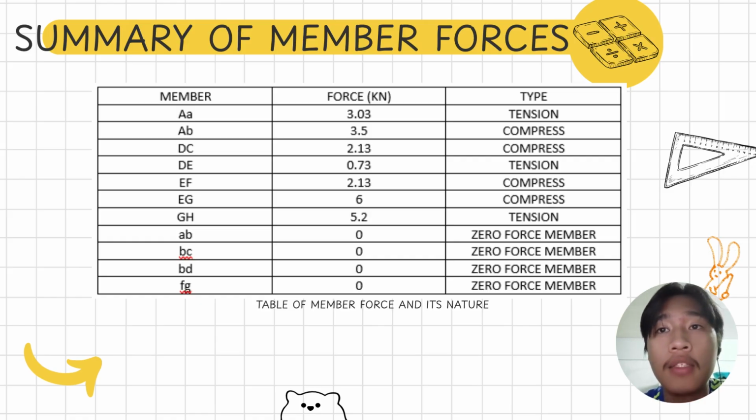designed. Lastly, members AB, BC, BD, and FG are identified as zero force members, meaning they carry no internal force under the given loading conditions. However, these members are still important as they help maintain the overall stability and geometry of the truss. In conclusion, this summary helped us identify critical members under high tension and compression, as well as zero force members, which is essential for efficient and safe structural design.